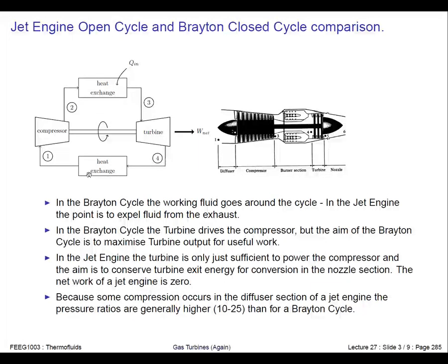So the reason that's difficult for a jet engine is that we don't have any kind of recycled air going around a loop here. So the air coming in here is cold air moving at a certain velocity, goes through all of this stuff, and comes out of the exhaust again with a different velocity, kinetic energy, and a different temperature. And we can't handle the fact that the kinetic energy going in and the kinetic energy going out are different using the system basis, because the system basis doesn't describe kinetic energy because it's a system.